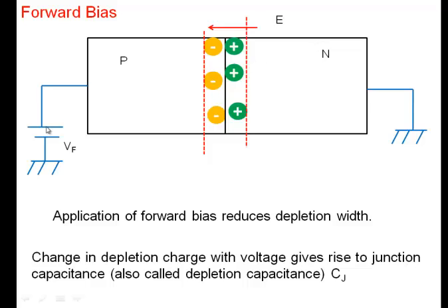And then they say, well, when you apply a voltage of 0.7 or a little larger than that, there is no barrier inside the diode, and then the current flows. Alright, so this is a very mistaken conception. That's not what happens. What I want to clarify is that the voltage inside a PN junction is Vbi, the built-in voltage. It's not 0.7, its value depends on the doping and all that. A better value would be, let's say, 0.85 volts.